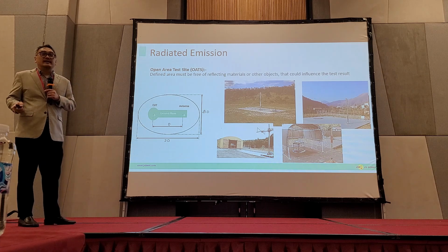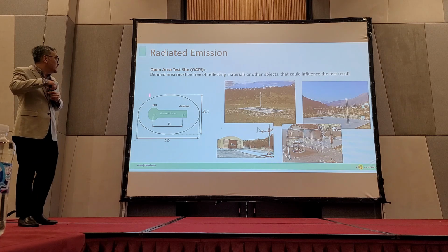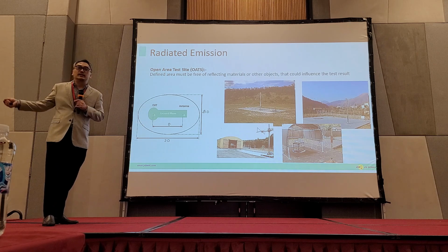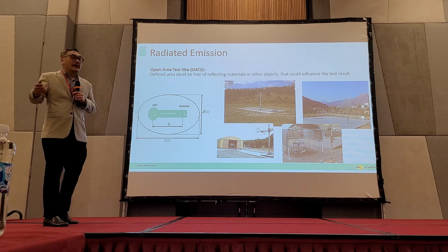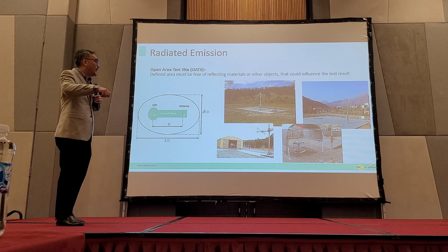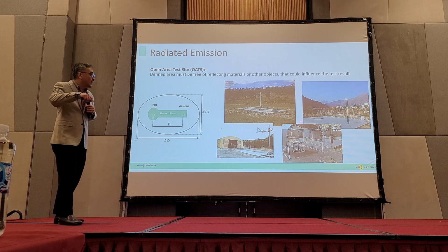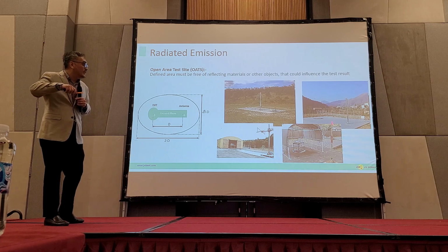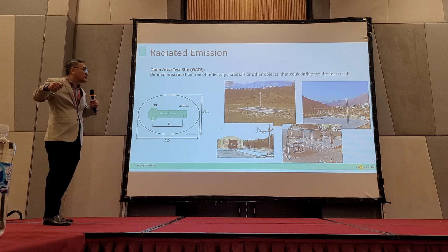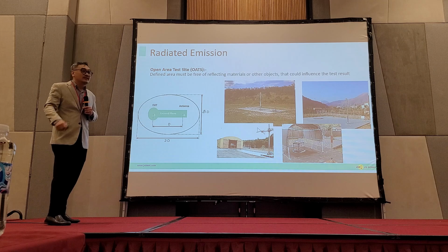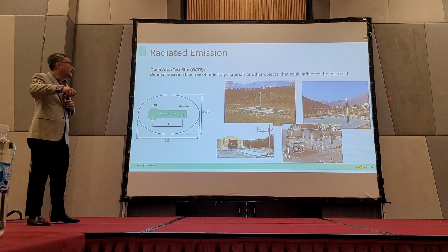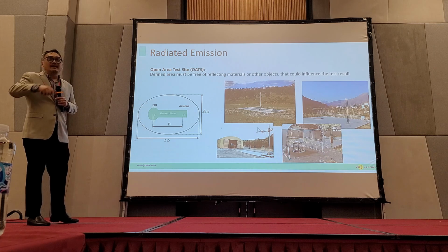Generally, in the olden days, we did measurement in the open area test site. I'm not sure if anybody has seen or used an open area test site before. It is just an open area where you make a ground plane, then you can turn your product, and your antenna can move up and down from 1 meter to 4 meter. The best part is the environment is good, clean from external noise, and there is nothing at the site.